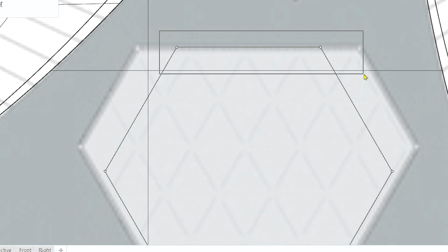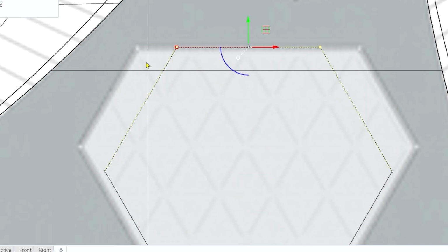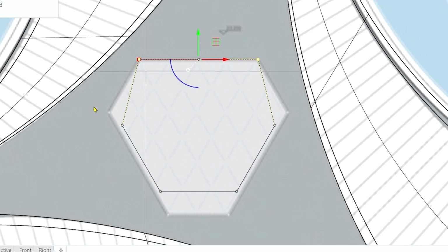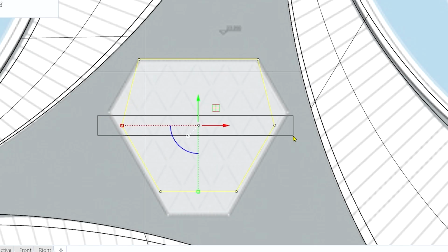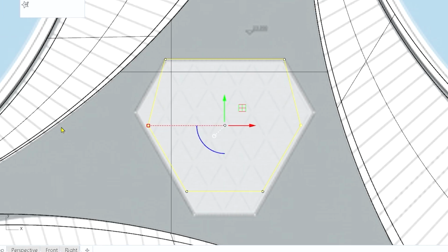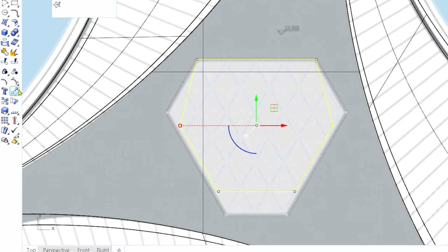So currently I want only to extend in these two directions, so I will not use the shift key. I can straight away just extend them on this axis. Same way these two, so control shift, right, control shift. If these points are not visible, you can go to the sidebar and use this show object control points, left mouse button, and if you don't want them, you can use the right mouse button, and all the points will go off, right.